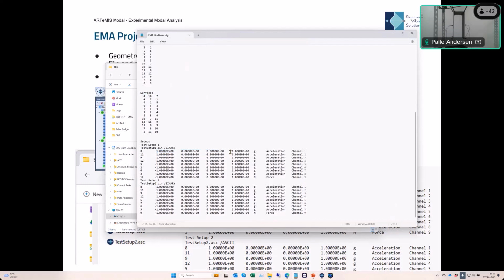Then there is a value here that we don't really have to care too much about. It's just the dB reference value that we use in order to make diagrams in frequency domain. When we want to show them in dB scale, we normally have to divide with some number, and that number can be defined by standards, but normally we just put it to 1 because it has actually no meaning. It does not in any way affect the results that you get out. So just put 1 if you are not able to find better values.